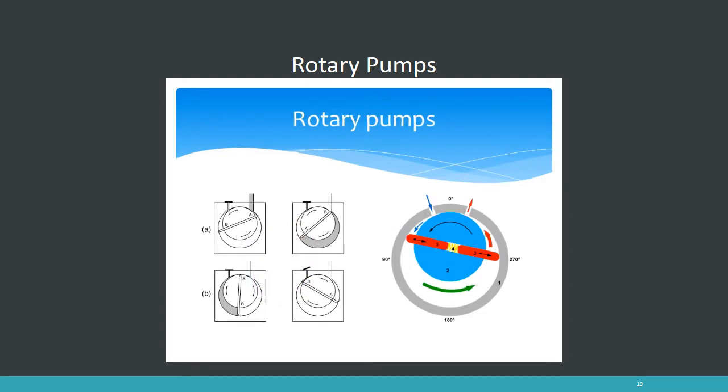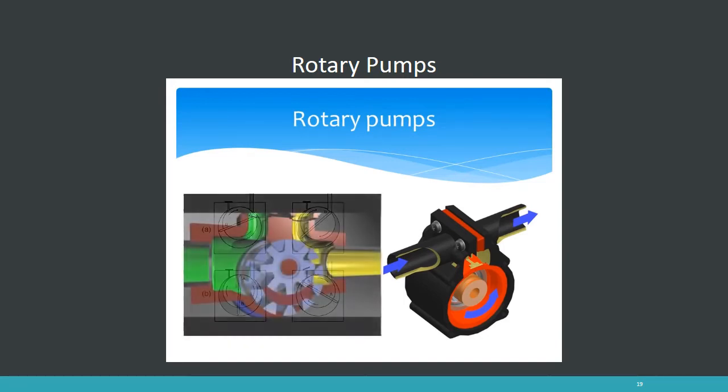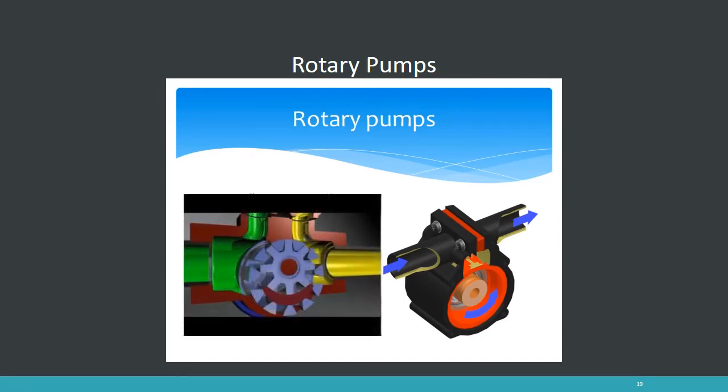The chambers are sealed off from suction by close clearance between the rotor and the housing, or by close clearance between intermeshing rotors. Rotation of the shaft moves the chamber along the bore or housing towards discharge. The chamber is displaced to discharge by rotation. The release to discharge progresses with rotation, as the volume is expelled, so that the flow is typically pulsation-free.